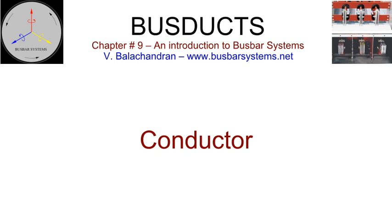In medium voltage bus ducts, copper or aluminium conductors extruded or formed in the shape of a channel are also used. Such shapes help increase the section modulus to enhance the load withstand capability of the conductor, lower skin effect ratio, apart from providing more cooling surface area. Flat conductors of large dimensions are supported in a vertical orientation. The support facilitates the sliding of the conductor, both at the top and at the bottom. Single channel or double channel in box formation when used are supported by a single post insulator with provision for axial movement.